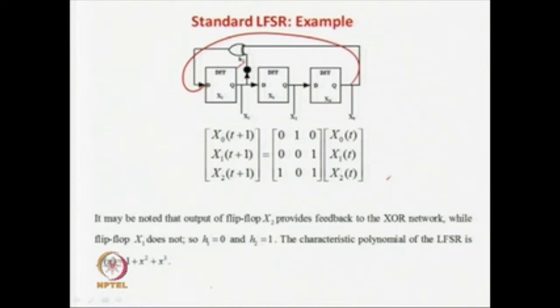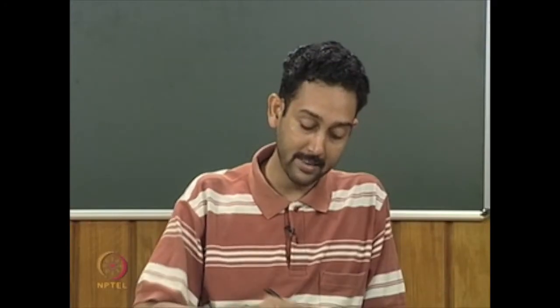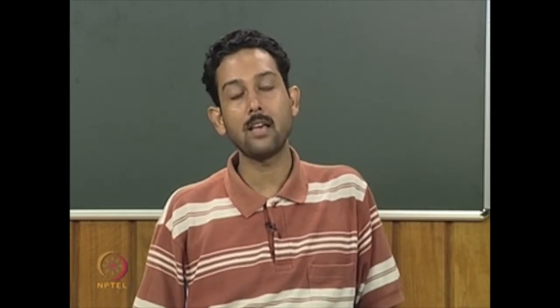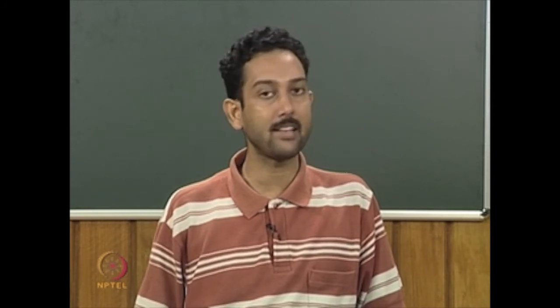Now, an important thing you have to know is that the theory is there. If you study this, you find out what type of characteristic polynomial it is. It will tell you that this is the characteristic polynomial which can generate all exhaustive test patterns. That theory we are not going to do here, and there is also a list. If you look at the references, some standard references are already uploaded in this web course. There are some standard textbooks, which give an appendix or a list of characteristic polynomials which are exhaustive in nature. These lists are available, and are proved in theory to generate the exhaustive test patterns, excepting all zeros, of course. So, you can select appropriately as you want.